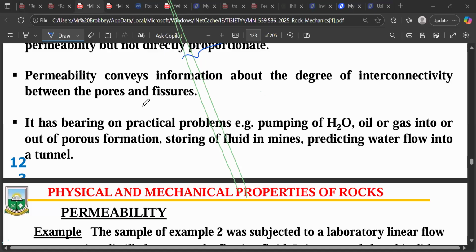So when you get to that section, what the geotech or the rock mechanics people do is increase their support system. You get it? Because if you don't increase your support system and you see that there is a lot of porosity, a lot of movement of fluids or water from the rocks, at the end of the day it can easily collapse. It's like water at the back of your wall, trying to push, trying to push. If you don't take care of it, one day you come and your wall will be down. So that's an example underground. The deeper you go, you try to increase your support system so that the porosity in that section can also be reduced. Thank you very much.